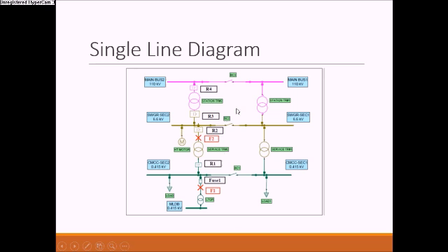Suppose a fault occurs at the position of relay 1. Then relay 1 will operate, then relay 2 will operate, then relay 3 will operate. The main problem comes when the fault occurs in between any two relays. Then relay selectivity and discrimination come into the picture. If a fault is in between R1 and R2 and nearer to R1, then we will provide certain time settings so that R1 will operate first and then R2 will operate. By that we give relay coordination so that they work accordingly. Next we will explain this in ETAP.